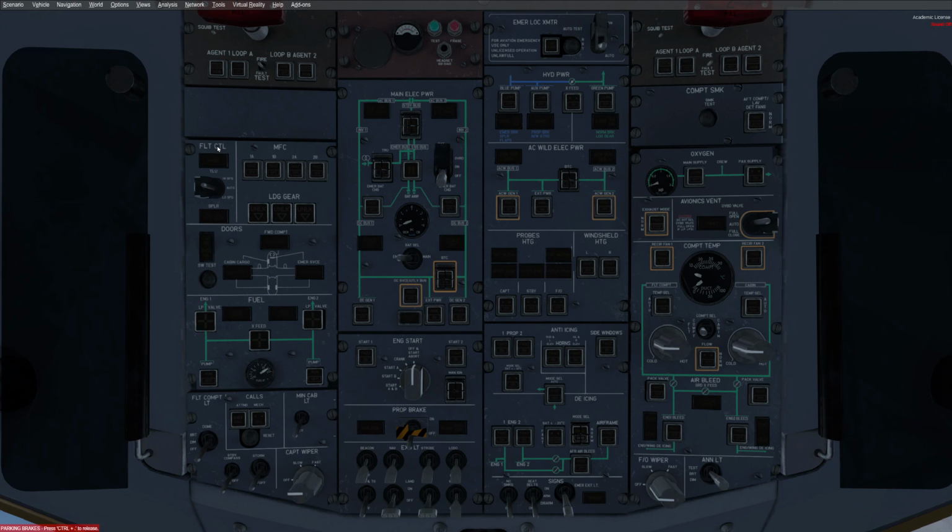So in case you're interested, up here on the overhead is the flight control. It controls the rudder movement, so it can narrow or widen the range of the rudder travel. Leave it on auto. Based on air speeds, it'll limit rudder travel. High speeds limits, slower speeds expands it. Landing, particularly important. If there's a fault, you can manually put it on low speed, and that'll improve the rudder travel for more control on approach and landing and taxi and all that kind of stuff.